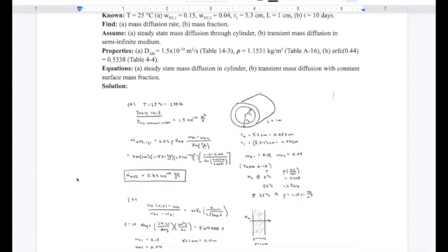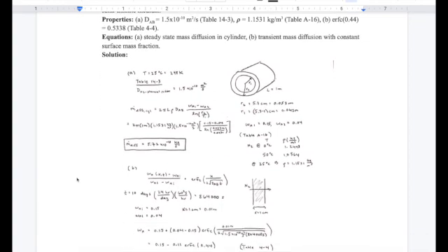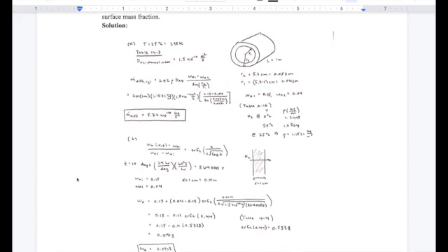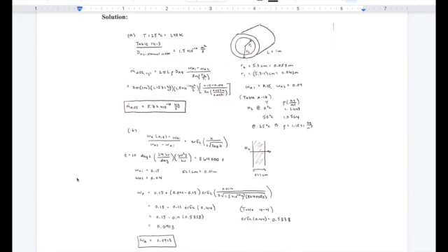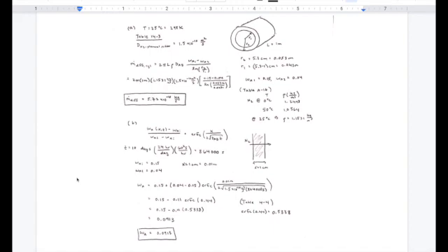In Part B, you assume transient mass diffusion in a semi-infinite medium, learning outcome 6B, and therefore use the error function equation to calculate the mass fraction after the specified time and with the specified thickness. The mass fraction of N2 that you find is 0.0913.